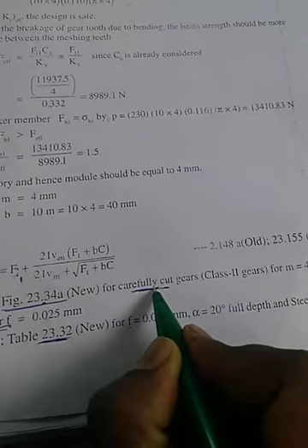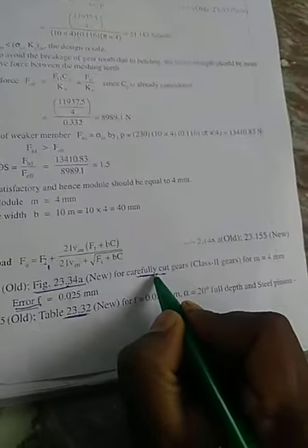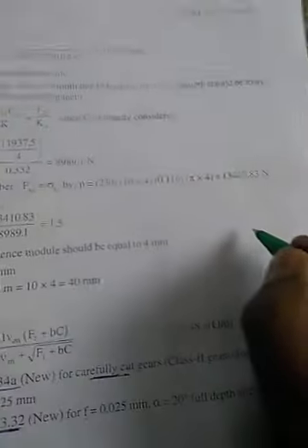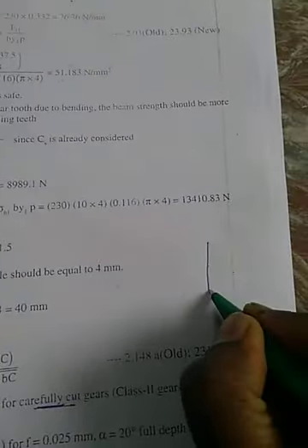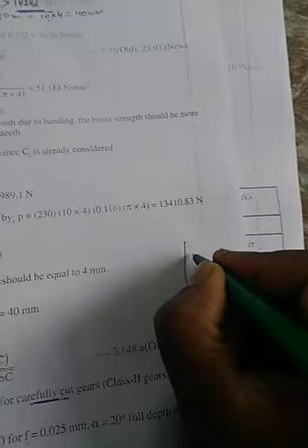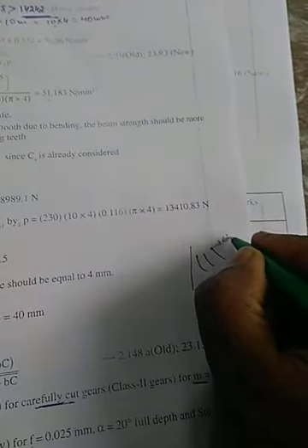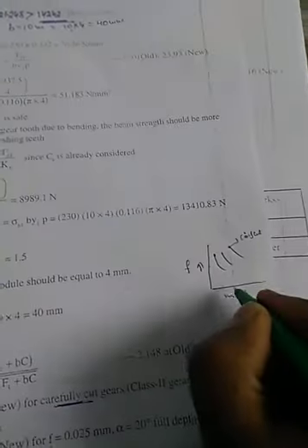So by using this, and by using the module, we will get a figure like this. We will get some curves. These curves are for carefully cut gear; you will get three to four curves. Here we get the module and here we get F. So by taking module equal to 4 and selecting the curve we are having, that is carefully cut gear,